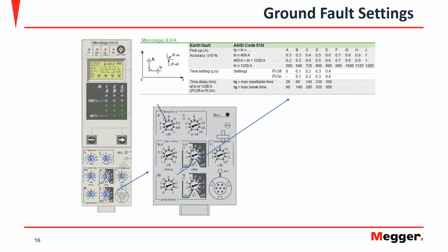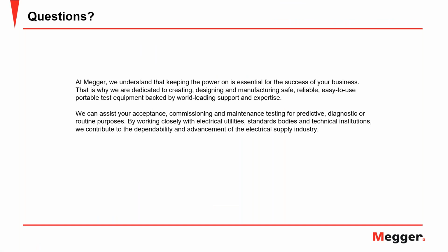Thanks, Daniel. So Jason, how do you handle self-powered type trip units where you need, for example, 30% of FLA just to turn on the trip unit? We run into this when trying to inject current through the neutral inline CT. Do you need two current testers?